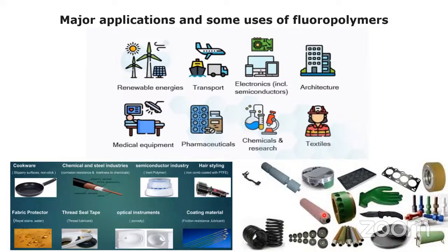Is it like paint? It is not painted. See, whatever you see on cookware, it is coated. The PTFE or polytetrafluoroethylene or fluoropolymer has been coated on your cookwares, meaning it's applied on it. You can't say it's always in liquid form. If you want to coat some polymer and it is in a solid state, you will melt or powder it and then coat it.